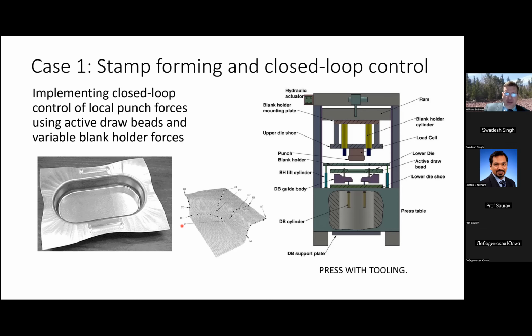of the stamp forming process to improve different components, especially the body panels of automotive. And we were trying to look at improving the formability of either high strength steels, thinner steels, and aluminum. And so my work focused on an aluminum alloy. You can see a picture of what I was forming here in the lower left. We call that the racetrack die. It has semicircles on either end and then a straight region.